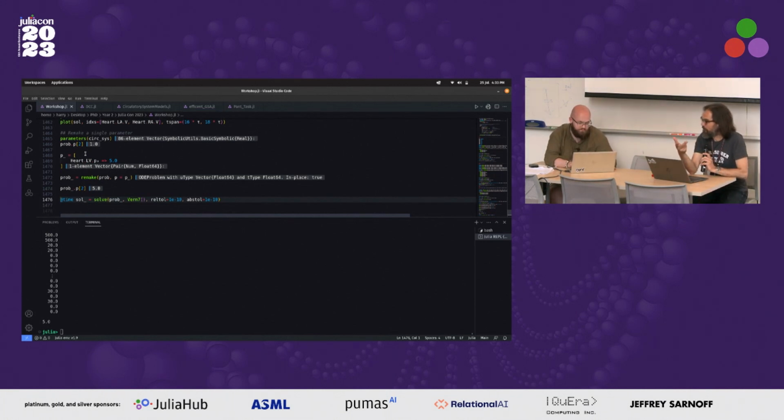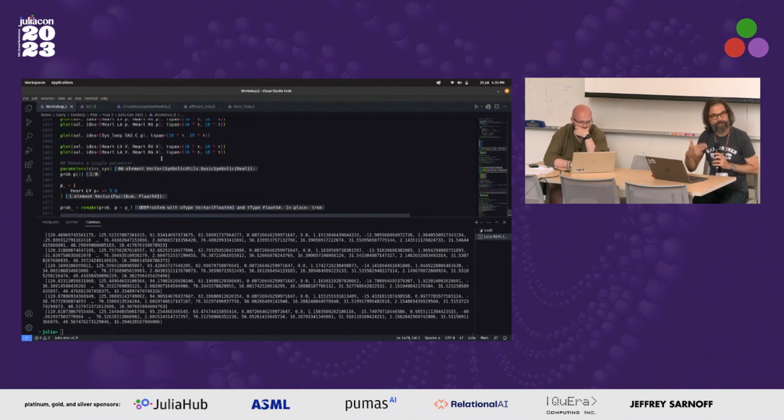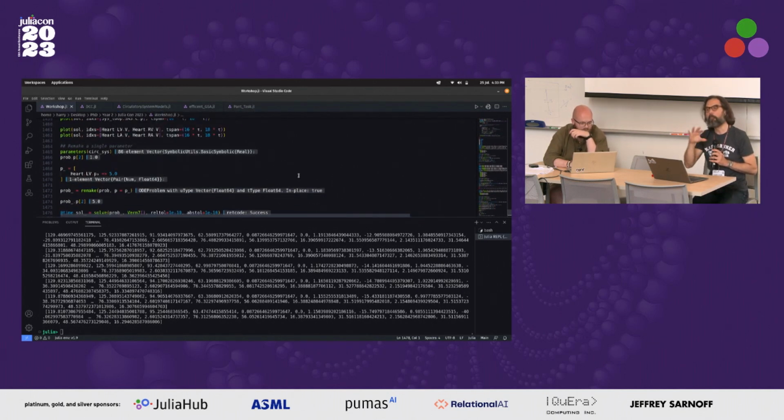If you haven't worked with ModelingToolkit before, you don't actually define the problem anew when you do a parameter optimization, because that would likely incur more compilation overhead, just-in-time compilation overhead. But the remake function, working on that pre-compiled object for the ODE, changes the parameters or the initial conditions out. So that's the trick that you need for having that quick runtime for all your 100,000 optimization runs.